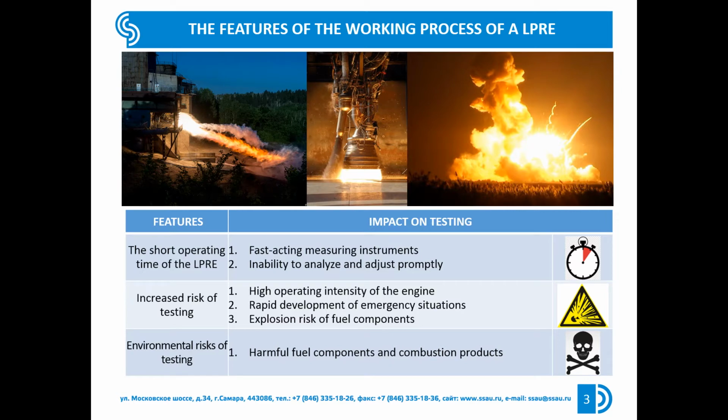The short operating time. The operation of a rocket engine on a single startup typically lasts from a few seconds to a few minutes. And during this time, the engine is started, several modes of operation in terms of combustion chamber pressure and fuel ratio and other tests are performed. The short operating time excludes the possibility of analyzing and correcting the cause of the test while it is in progress. Therefore, tests must be as automated as possible, and the measuring instruments used must be fast but also have a high degree of accuracy.